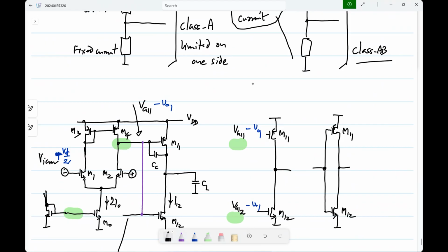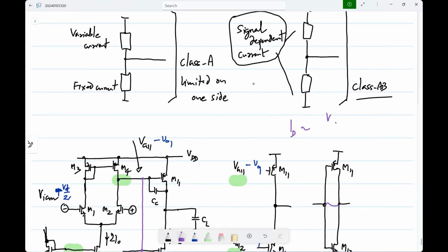In general, if you connect it up like that, the current will be dependent on (VDD minus VTP minus VTN) square. The proportionality constant will be something complicated, you can calculate, but it will be very strongly dependent on the supply. That is the other feature of the CMOS inverter anyway. The CMOS inverter's current is strongly dependent on the supply. Okay.